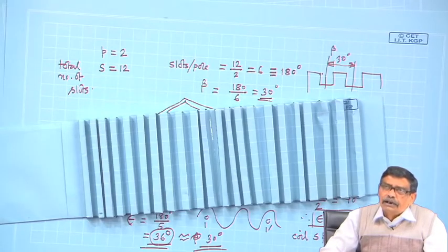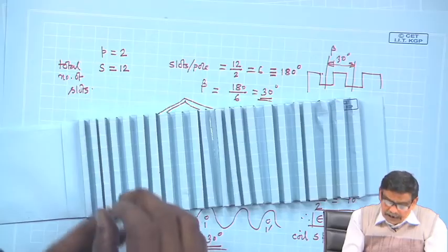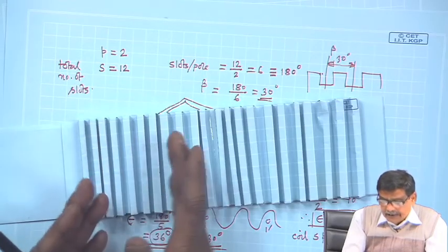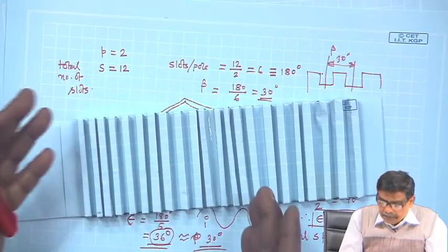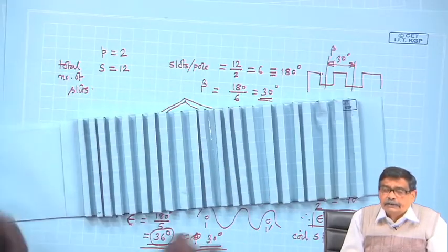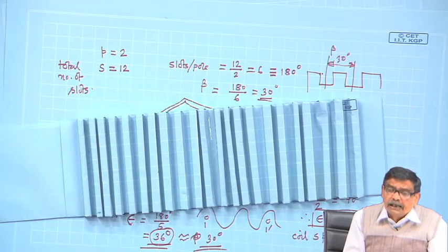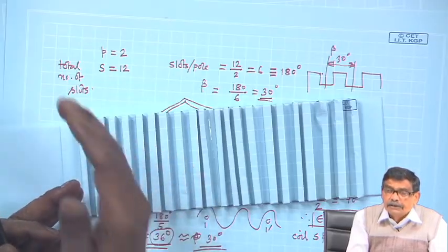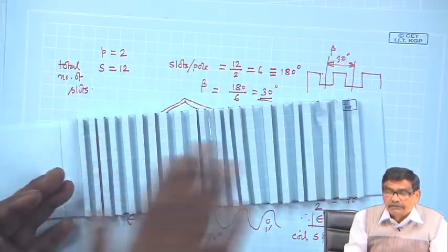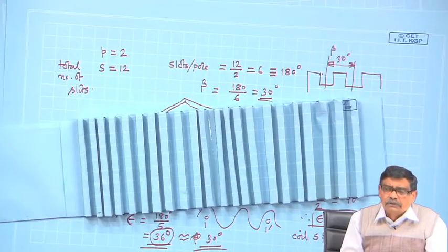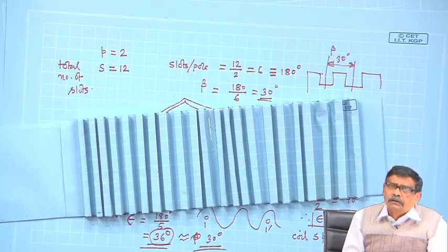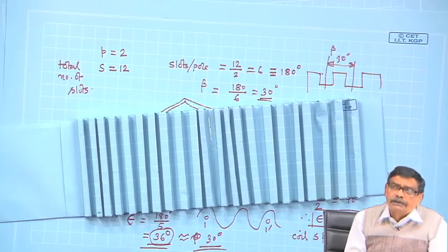But we have shown that if many coils are displaced in space and connected in series, instead of keeping all the coils concentrated, the MMF distribution can be made stepped, more towards a sine wave. So the effect of harmonics will still be present, but considerably reduced.